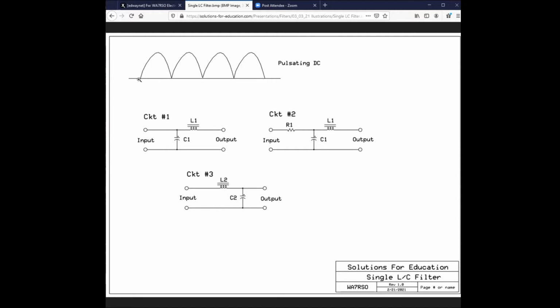Something else that we need to look at. If you look over here, the rate of change here is greater than here, and greater than here, and greater than here. And finally at the top, it's rolling over the top. And what is our rate of change up there? None, zero. So at that point, what is the counter EMF being developed? Nada. So one of the things we can look at, if we had time to do so, because in the classroom I would spend several days on this entire topic, is drawing graphs of what the counter EMF is as this voltage and the current are changing.